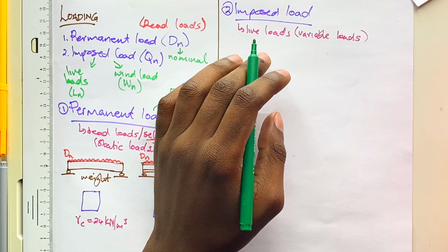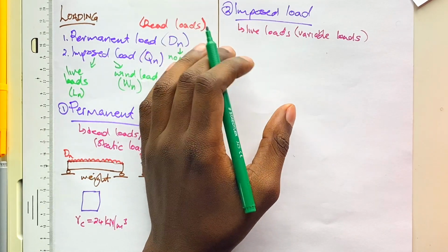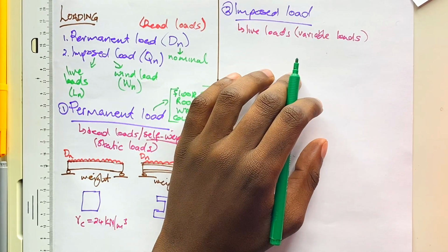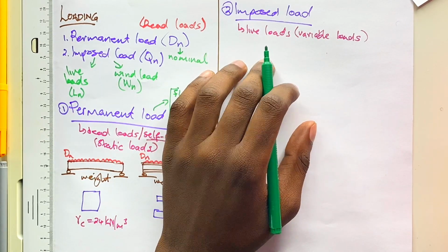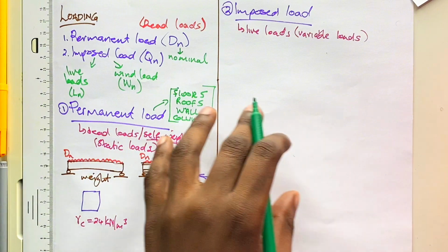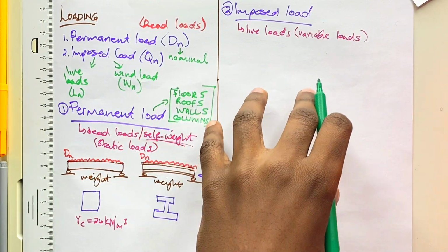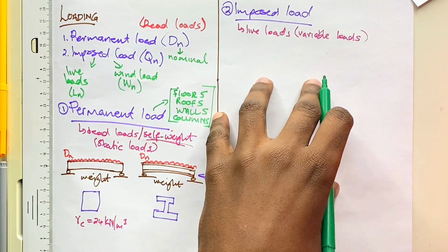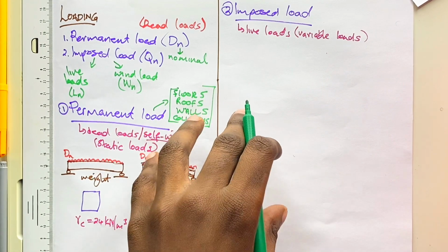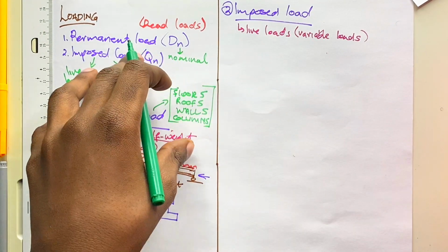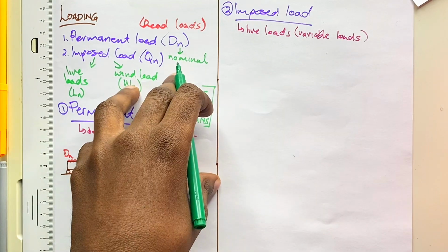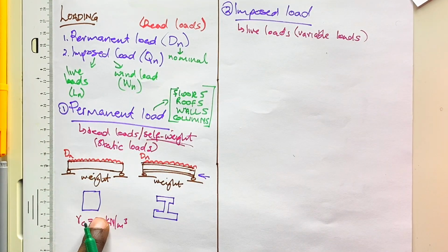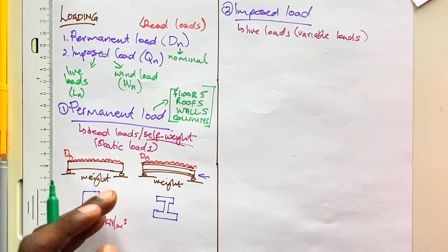For instance, the live load in a residential area would be different from that of a concert hall, gymnasium, or office space. Different activities lead to varying loads that structures must accommodate. So calculating these live loads involves determining the maximum expected load based on the occupancy or the function of the space.